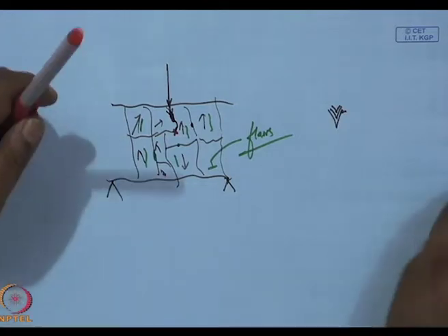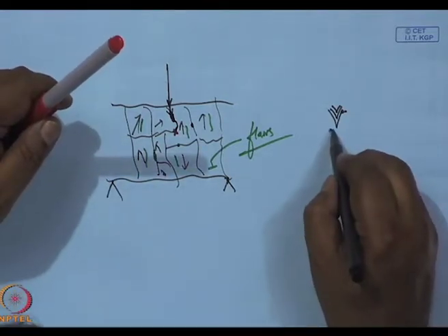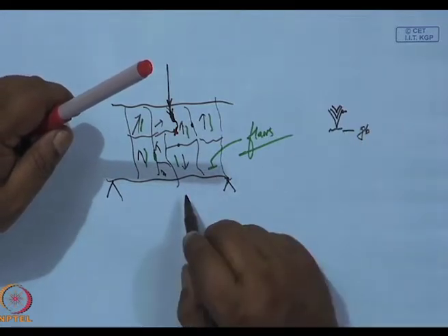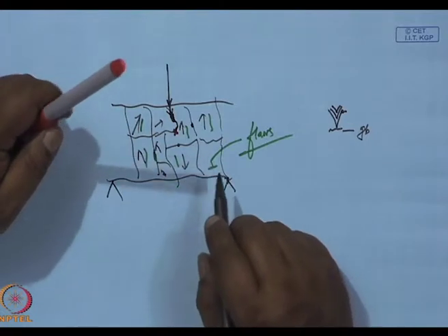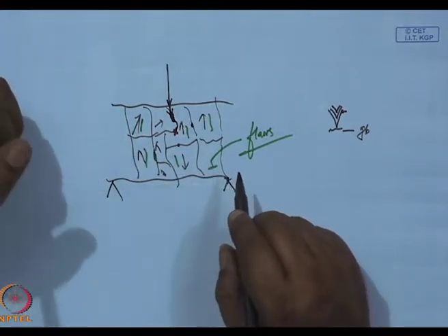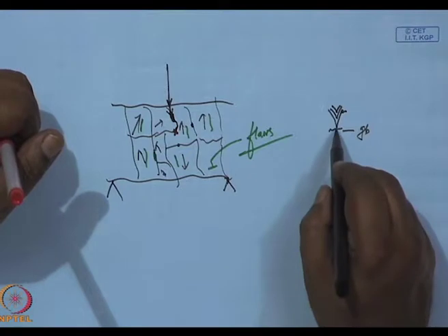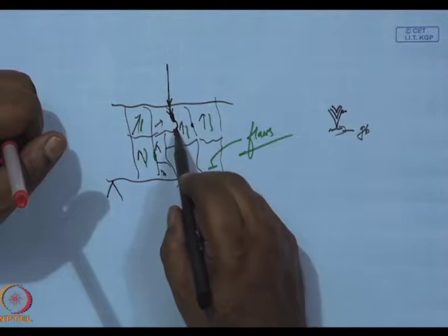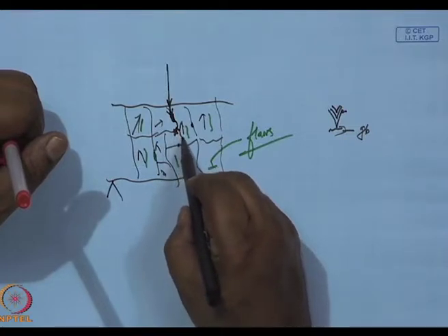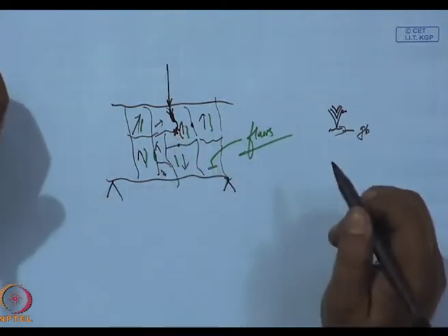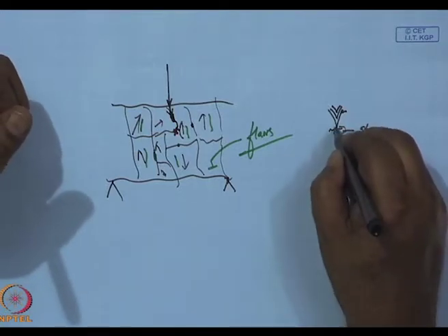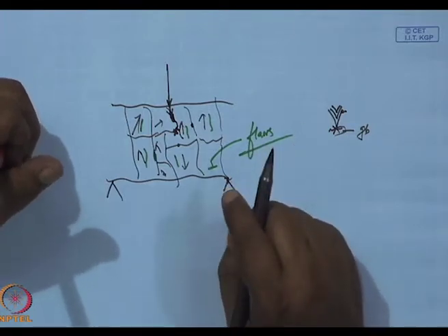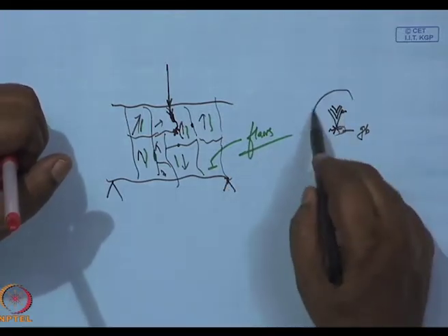What can happen here? The propagation of the crack can stop. The crack can go around the grain boundary, which is over here. It could have taken this turn also, or it could have generated many more cracks, which again prevents the flaw from going ahead.